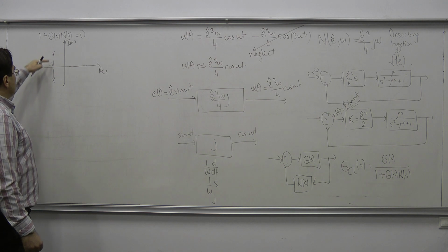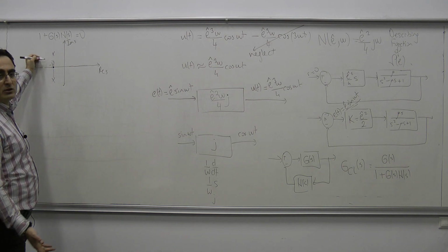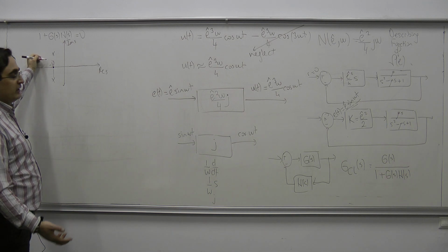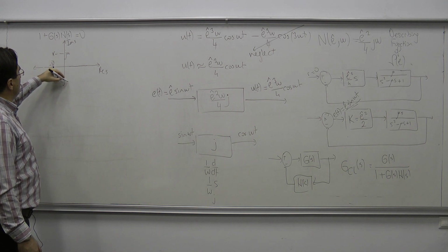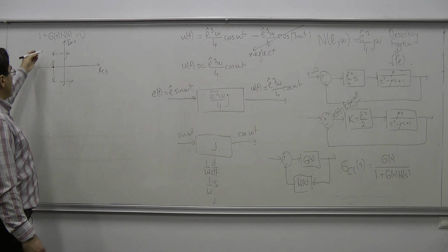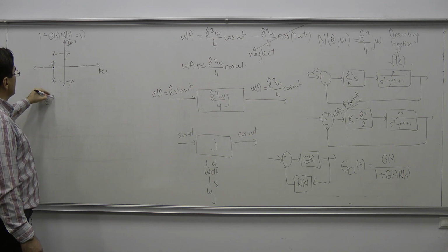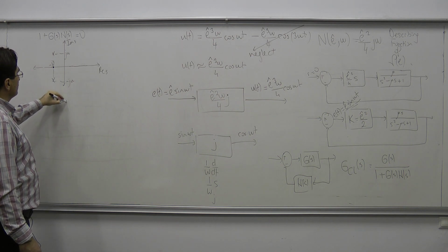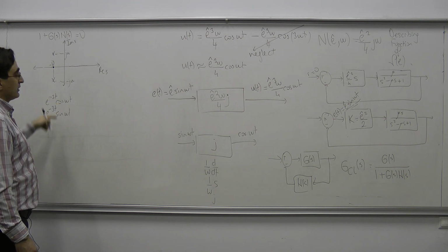Remember that real part of closed loop poles would determine the decay or the growth rate of the oscillations. So if I have closed loop poles like this, then that means that in the response of this system, I would see e to the minus 3t cosine omega t and e to the minus 3t sine omega t like terms.